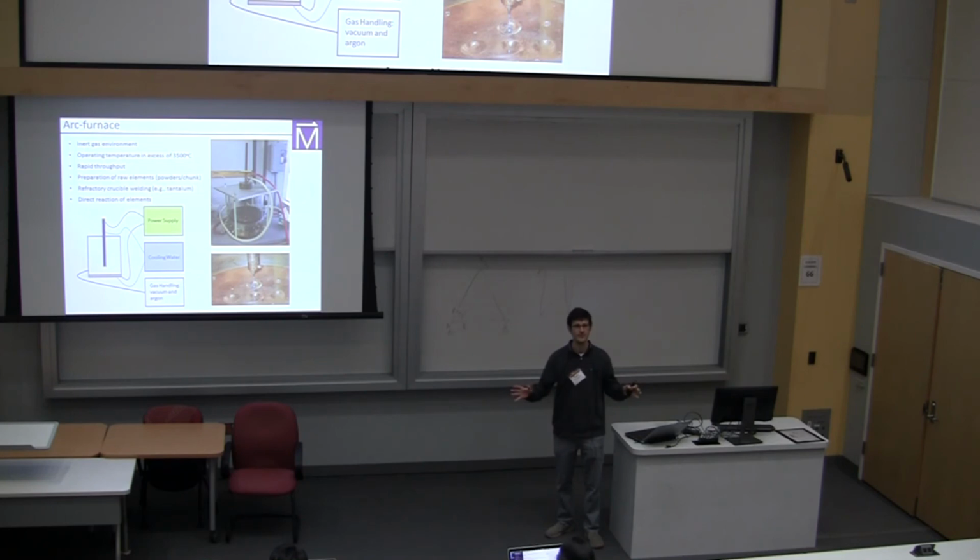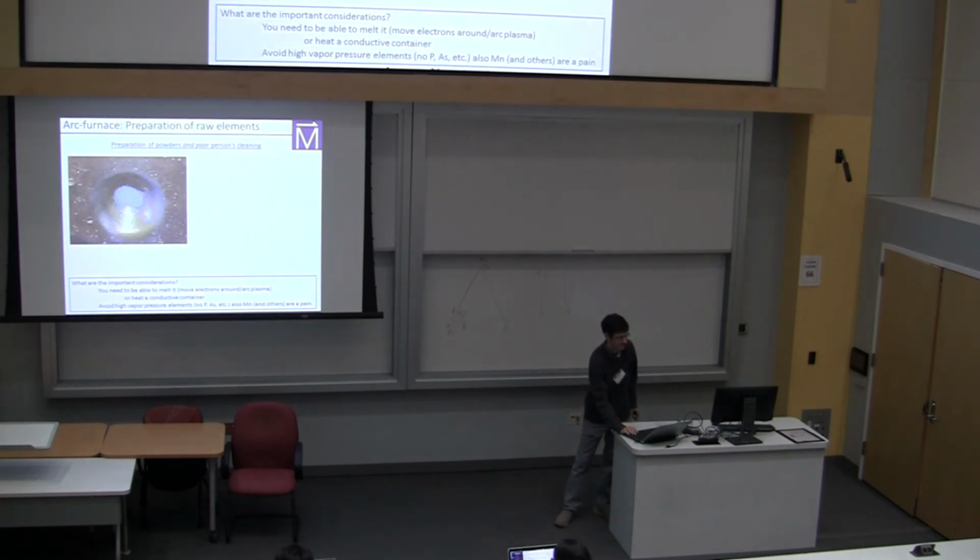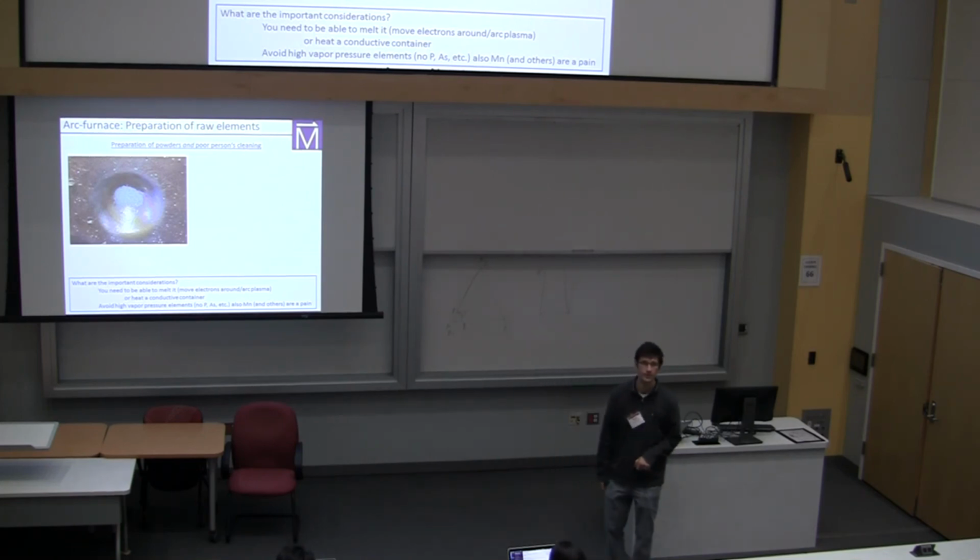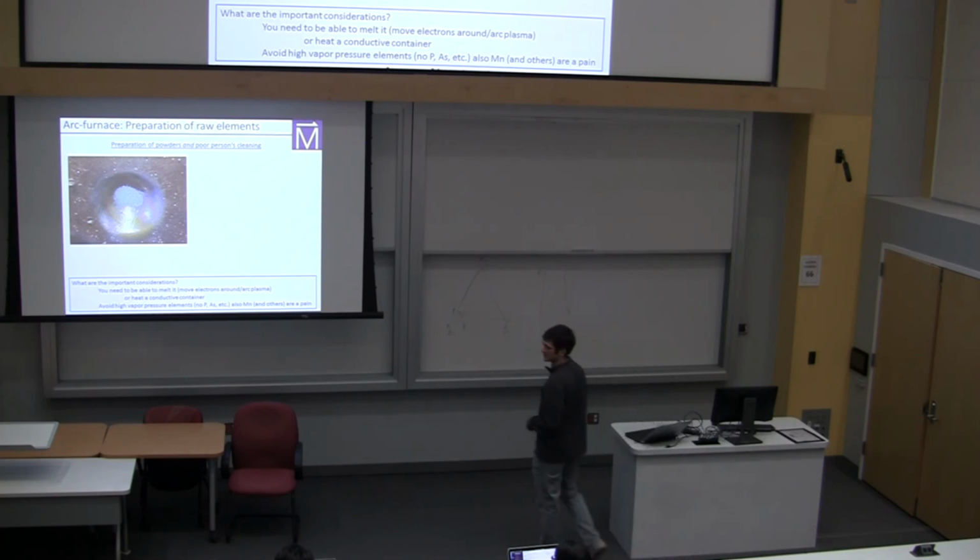Okay, so everyone knows about arc furnaces, and I'll leave it at that. Unless you have a few tips. Okay, quick tips. I'm not going to tell you what an arc furnace is. I'm going to tell you that one thing it's really useful for is preparing your precursors. You may sometimes have a powder or a granular form of something. You may think that it's very clean. I can tell you it's probably not unless you live in the high desert or something. It's definitely not true in Florida.